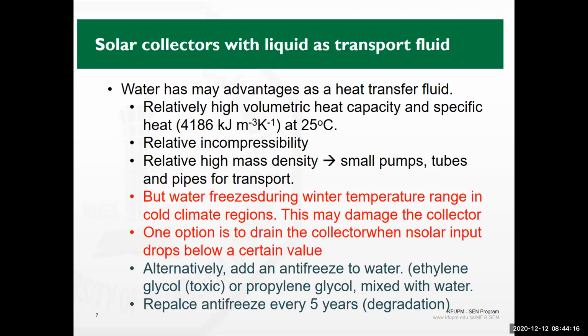in tubes. If you remember from our study of thermodynamics at the beginning of the semester, we were talking about the pumping power for water versus air. And basically it's the integral of specific volume times delta P. The specific volume for the water is very small. For the air, specific volume is large. That's why it needs larger power to drive air into tubes. Water is much easier. Water is incompressible. It has high mass density, so you need small pumps. Tubes are having small diameters, and pipes are available even in PVC, which is basically an insulating material.